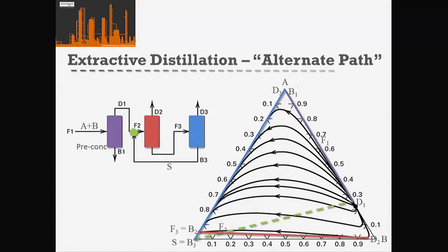So what we managed to do is to draw our whole distillation sequence, including our mass balance for the addition of the solvent, just using our ternary diagram.